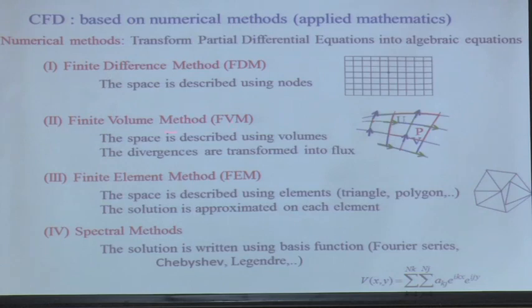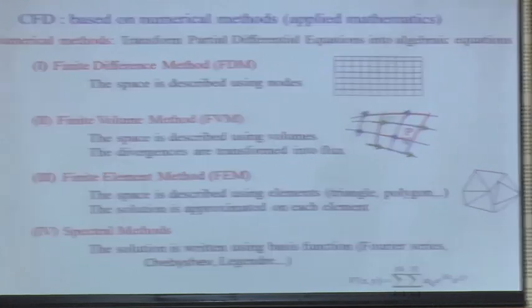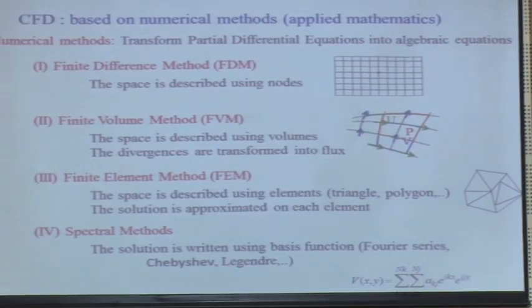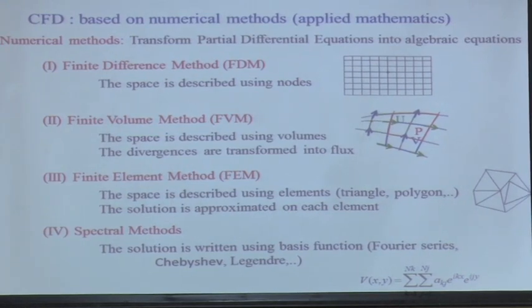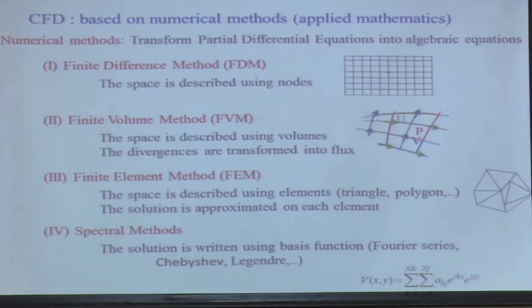And the finite volume method has this property to manage the balances, because instead of looking at the value of your system at one point, you are going to integrate over a very small volume all the different fluxes, the flux which are entering, exiting, and the rate of variation of your variable inside the mesh. Okay, so finite volume method is very popular for fluid mechanics, for CFD, finite difference as well.